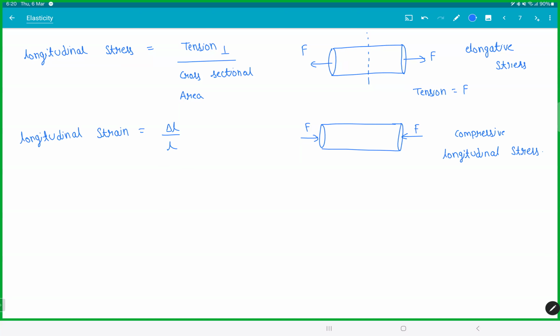Tell me one thing. If I have a 1 kilometer steel wire and a 1 centimeter rubber cord, and I need to stretch the 1 kilometer wire by 5 centimeters and the 1 centimeter cord by 5 centimeters, which is more difficult? The rubber one, right? Even the rubber generally stretches better, but the length is only 1 centimeter and you're trying to make it 5 centimeters. For 1 kilometer, 5 centimeters is easy. So again, the comparison is wrong. You don't study elongation, you study elongation per unit length, delta L by L. So keep this simple.